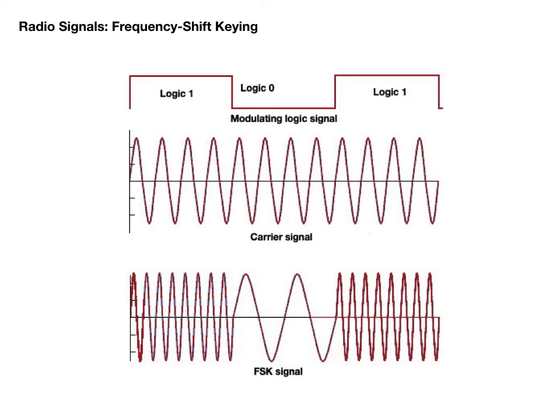To transmit digital information on the amateur radio bands, hams often use a type of modulation called frequency shift keying, or FSK. Radio teletype, or RTTY, is an example of frequency shift keying. An RTTY signal shifts between two frequencies called the mark frequency and the space frequency. The mark corresponds to a digital 1 and the space to a digital 0, or vice versa.